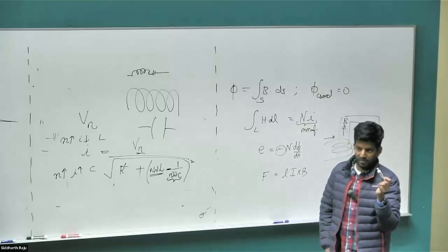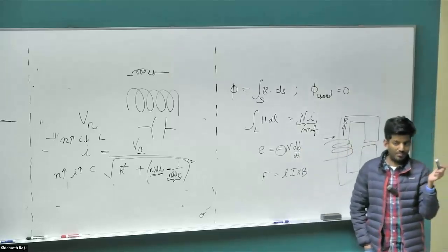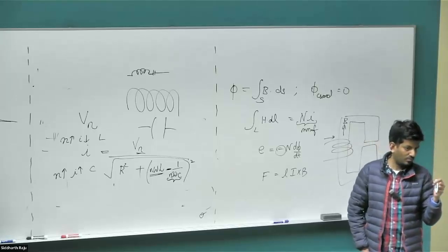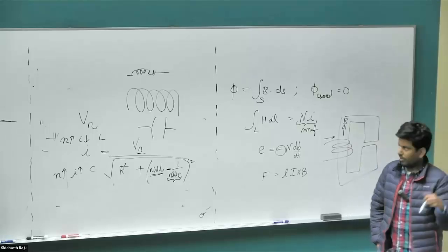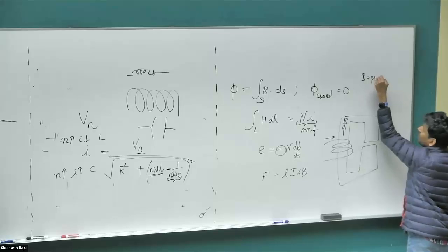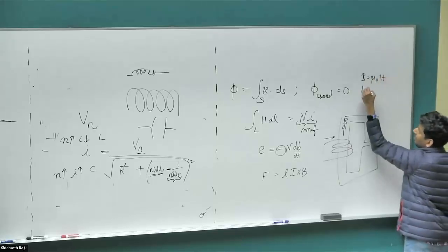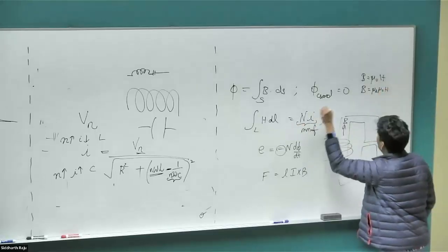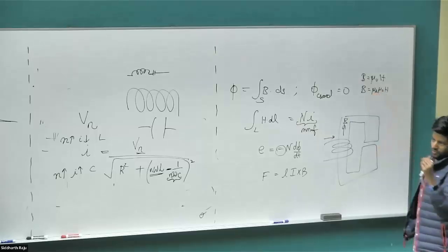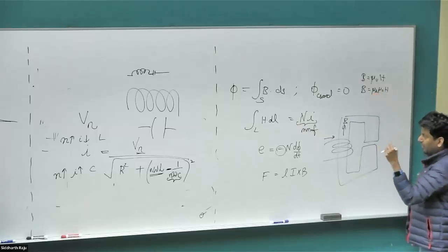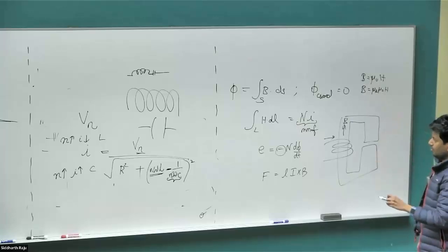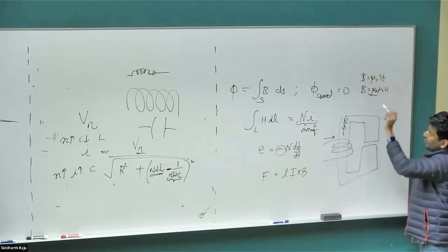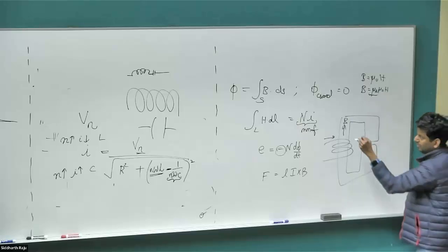Okay. What is the relationship between B and H for iron and air gap? Well, let's start with the simple case. What's the relationship between B and H in an air gap? Constant. And what is the constant? Mu naught. So B was just mu naught times H, right? And in iron, that would have been mu r mu naught times H. We introduced this H term instead of the B term because we do not know what this mu r is for different materials. It's very hard to figure it out for a single particular value. So we have those BH curves, elaborate systems, and so on that can model it as if it's a constant. So both for iron and air gap, B and H have the same polarity, right? B is in one direction, H is going to be in the same direction.